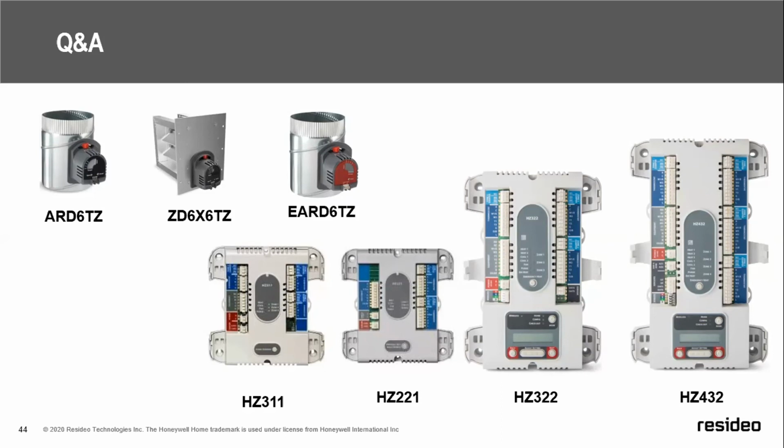You want to make sure the wires from the thermostat to the board are configured properly. The jumpers are in properly, both the inlet and the output. And when you use the installer test mode and bypass the time delays in the thermostat by having them in the installer test mode, you can quickly make sure that the zoning system does everything that you want it to do.